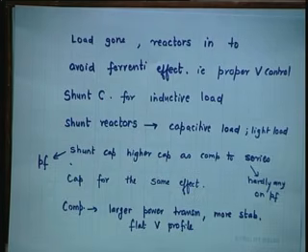Shunt capacitance, of course, is costlier. It is 3 times costlier than series compensation. If it is asked in an interview or anywhere, you can say it is very costly, but it does 3 jobs. So, it somehow compensates. What are the 3 jobs? Example 5.1, the solved one, gives you that. It improves power factor, it improves transmission line efficiency, and it also improves the voltage profile.